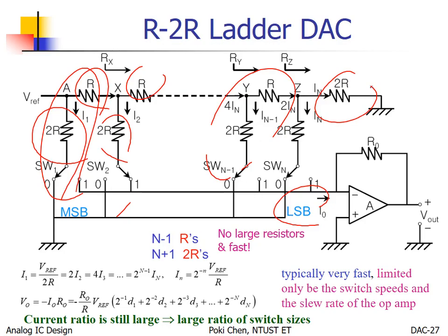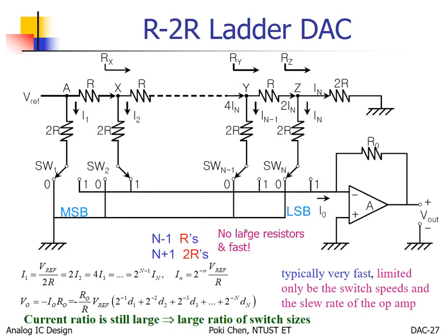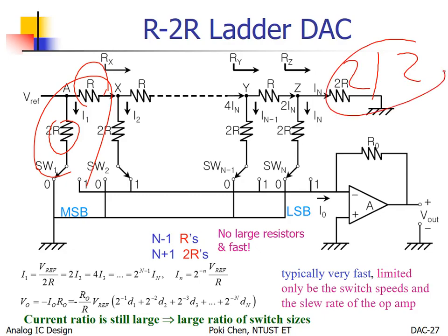The problem is, in the past, engineers didn't pay good enough attention to the area of such resistors. Usually we say, hey, for R and 2R, I need to match them, right? So you have 1R here and 2R there. Congratulations. And then, if they do a good enough layout pattern for 1 bit, usually the engineers will apply the same layout from MSB to LSB.